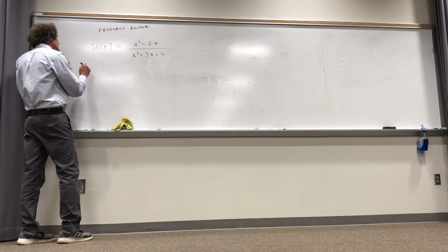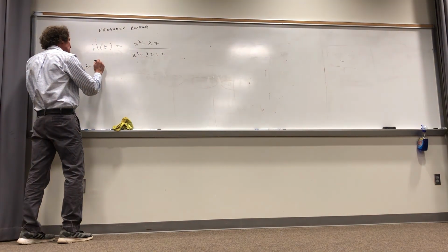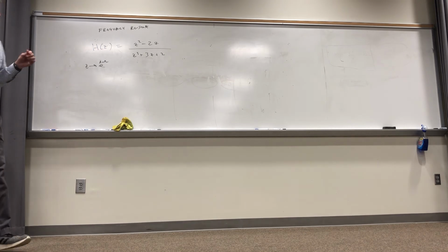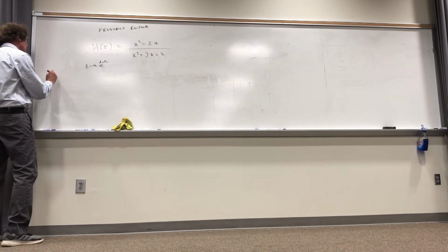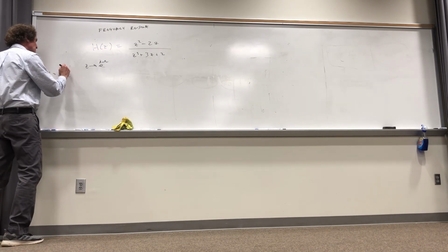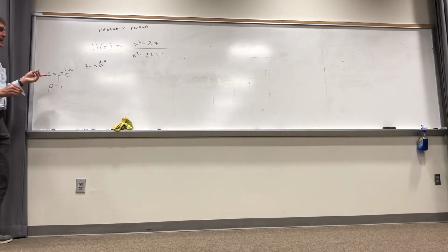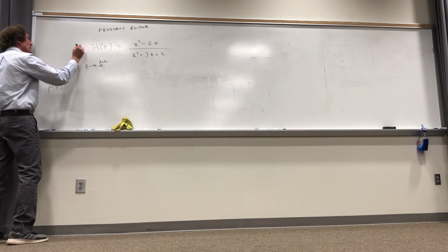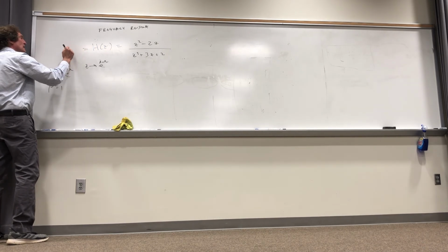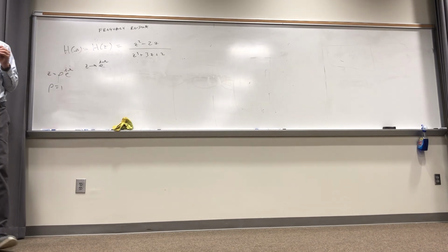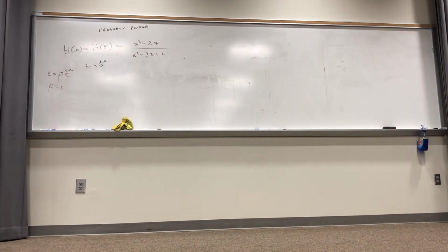The way to do it is let z be equal to e to the j omega. What that means is normally z is some radial distance rho e to the j omega. Here we just make rho equal to 1. Now, basically what you have is H of omega, which is really the DTFT of the system. Again, it's assuming x of n is 0 for values of n less than 0.